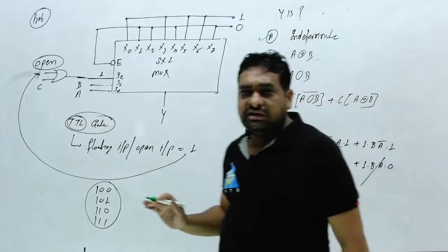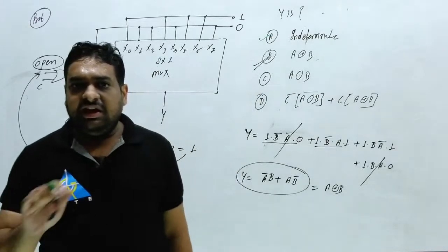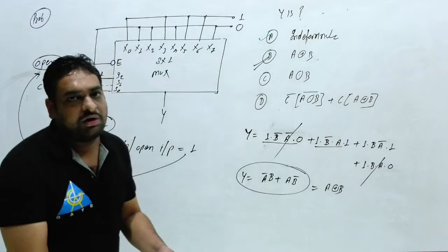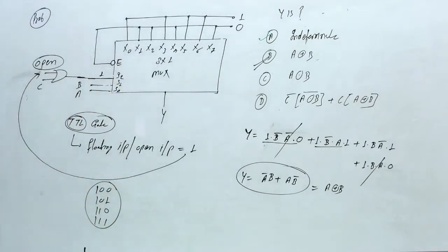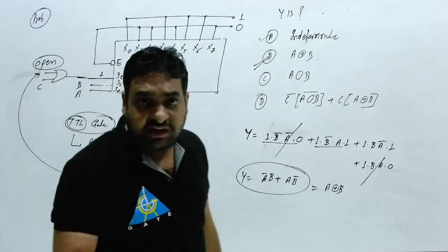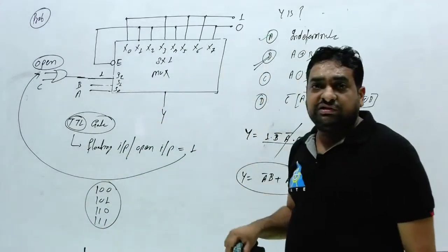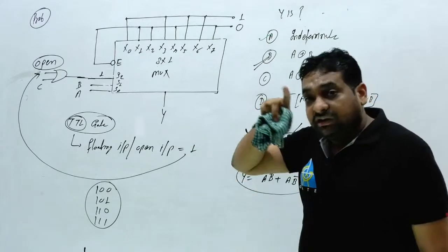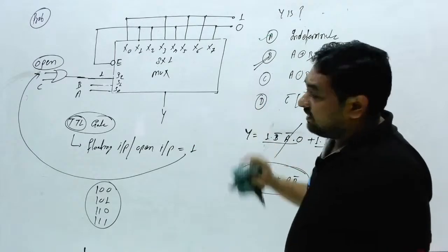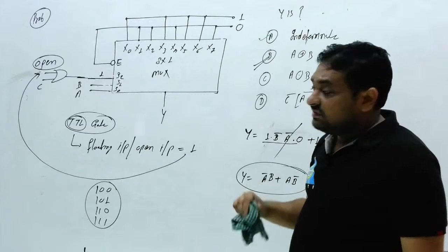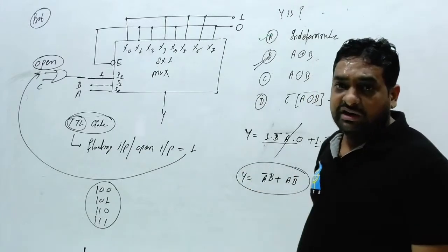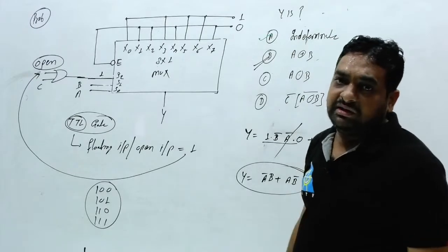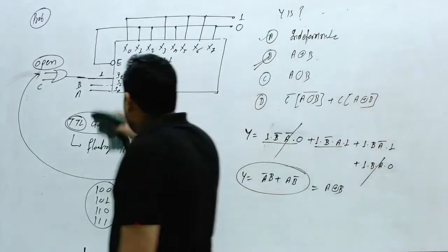In a CMOS circuit, you cannot treat any input as an open circuit. The circuit will practically not work. You should remember this. This is a previous year GATE question, and the same kind of question has been asked 2 times in the GATE exam. But if the examiner targets this question this year, most likely they can provide CMOS, and the result will be indeterminate. Clear?